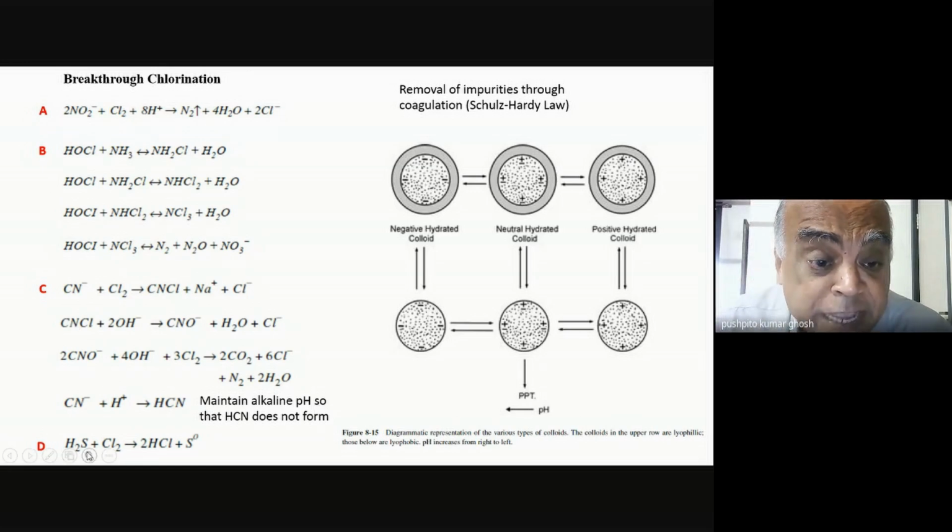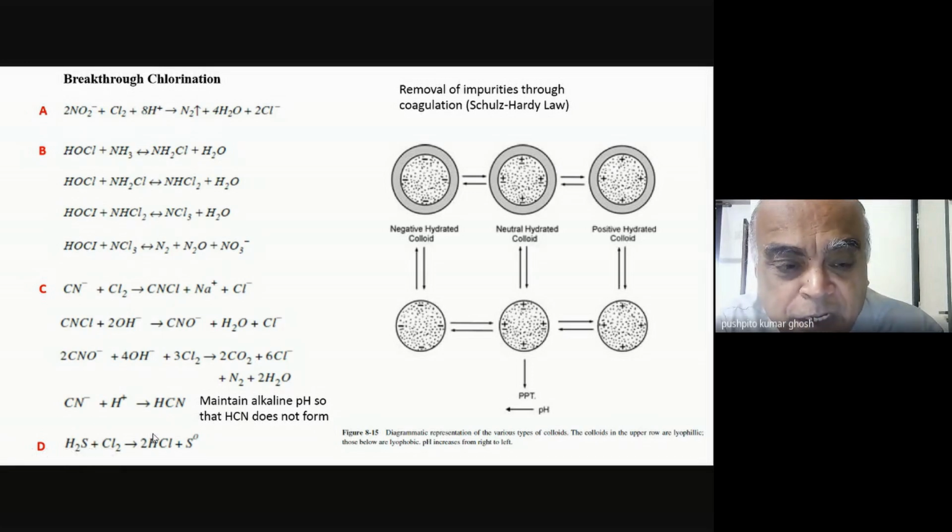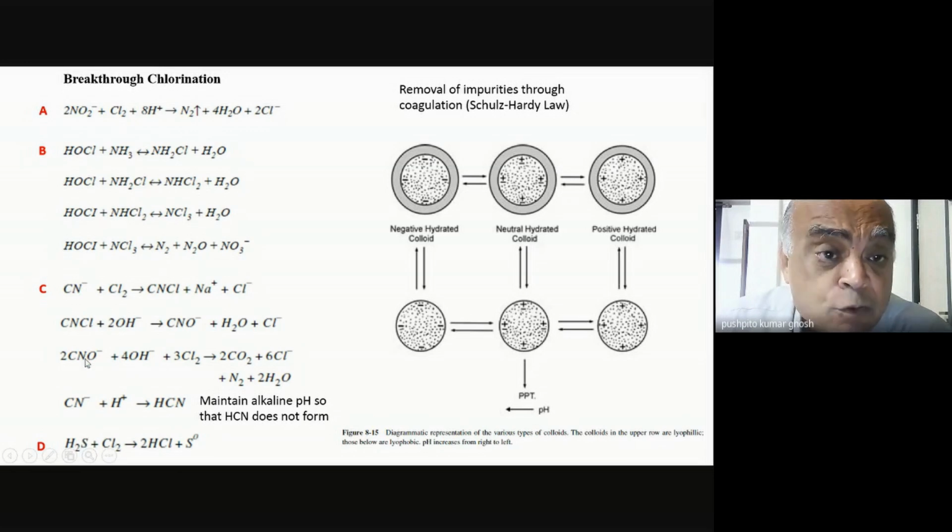Again, another one is H2S. Again, you can do an oxidation with chlorine. It's something like your Claus process, how you can convert H2S into sulfur. It's along those lines, or the Leblanc process modifications. And you can see now with one reagent like chlorine, look how versatile it is. Look at all the things that it can do. And in addition, of course, chlorine becomes very oxidizing, so it will also get rid of all your bacteria and germs and everything. So it's a wonderful chemical for effluent management.